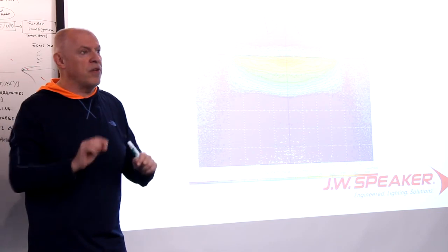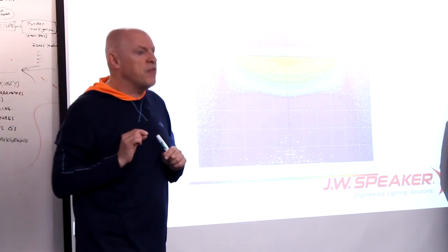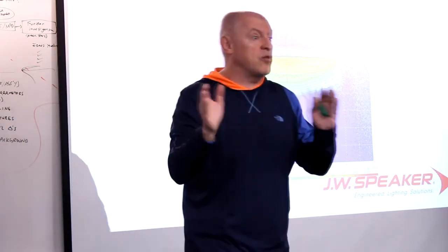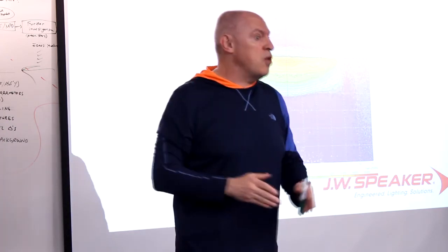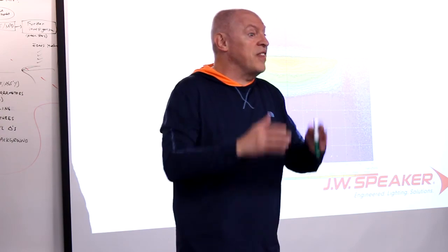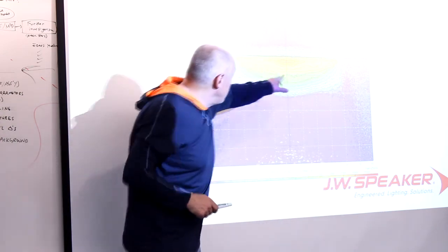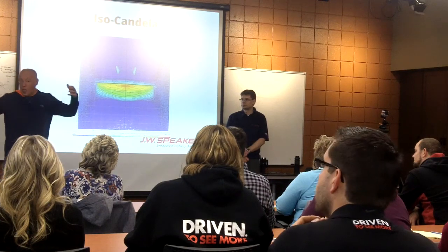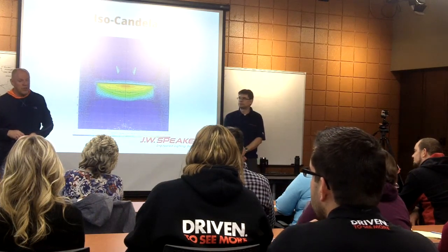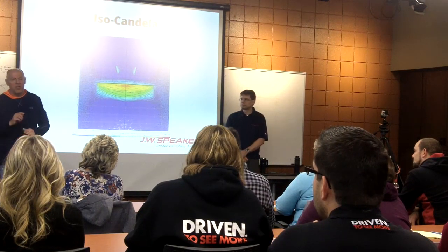If it is a low beam, you would like to have that 15,000 candela or 20,000 candela in that window. If it is a high beam, you would like to have 60, 70,000 candela in this small area. If it is a working lamp, it depends how big the working lamp is, but usually hotspot doesn't matter.